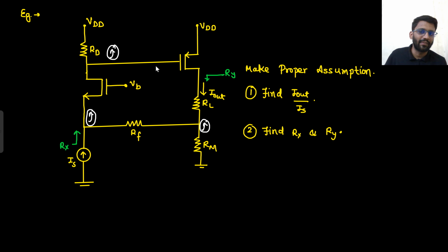Now what is this? This is a common source amplifier. We are going from gate to drain. So from gate to drain, this node will decrease. If this node is decreasing, then certainly this node will decrease. So what kind of feedback is there? It is a negative feedback.